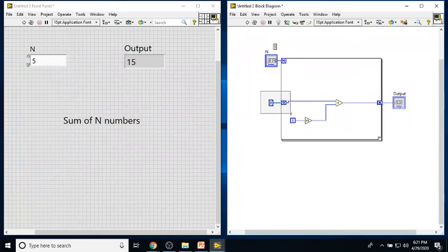It's always needed. The reason is, it will always start the execution from the previous output. Whatever you executed right now, once again when you try executing it, it starts from the previous output. So only for that reason, you should always try to use reinitialization of the shift register, right?